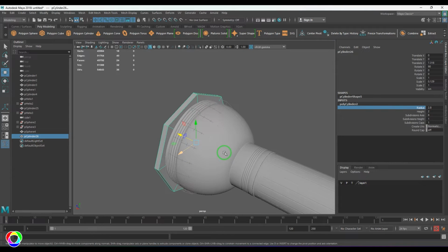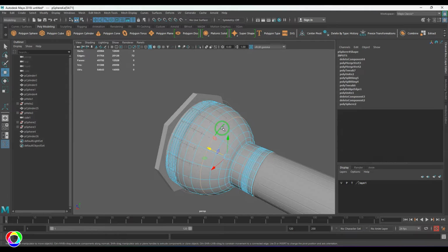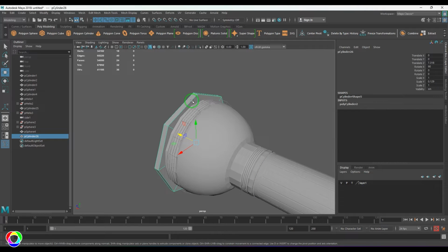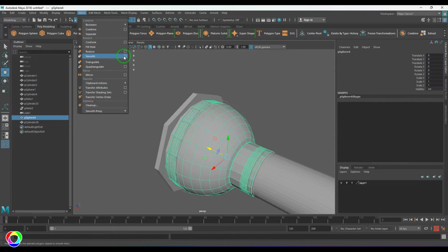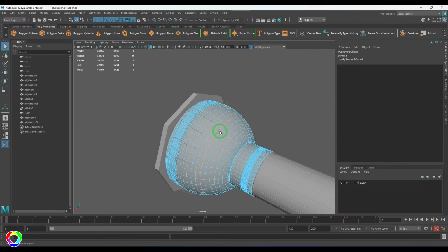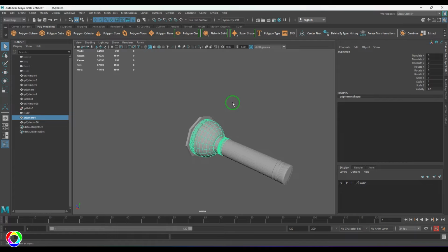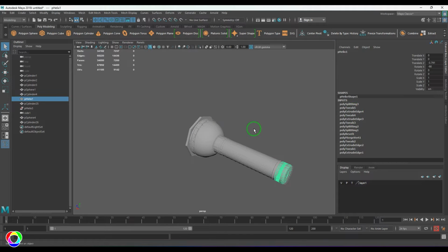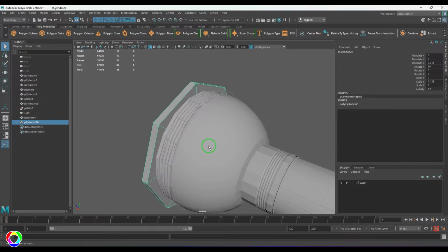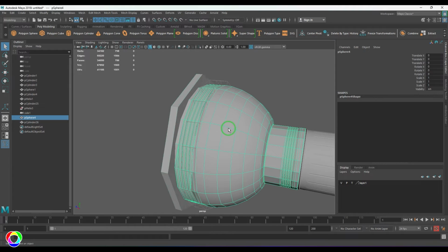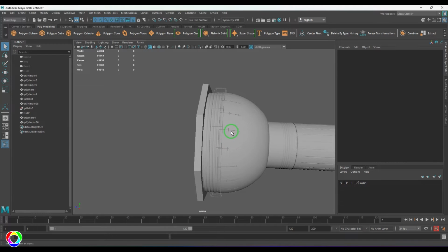Let's say if I subdivide it, these lines are 18, right? So here I need to have a very similar count. If not, I may end up getting wrong connection. So if I, let's say, apply mesh smooth of 1 and then subdivide it, this is 36. So this is one thing I have done wrong, which is taking an odd 8 number. That's a big mistake I have done here. So 8 2s are 16, or 8 3s are 24. So I don't get 18 there. Mistake. So I have to manage that mismatch.